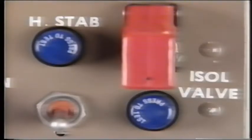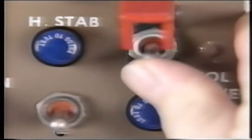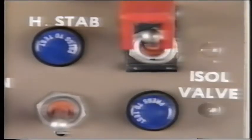To fuel the horizontal stabilizer tank, or HST, the guarded HST isolation valve control switch has to be in the open position. This opens the isolation valves in the center tank and the HST.